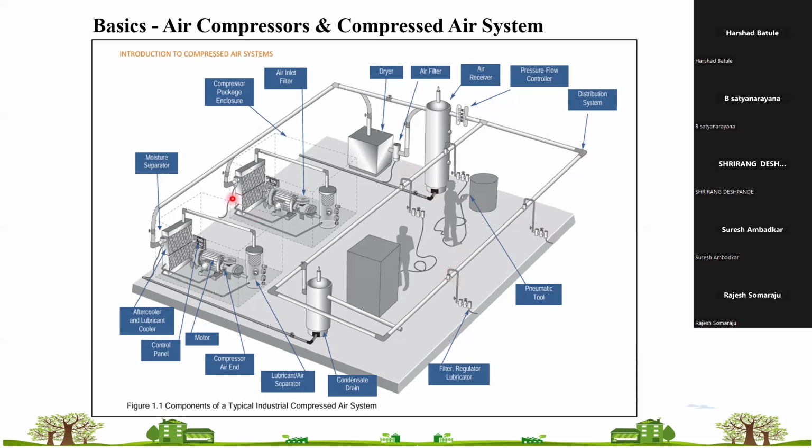You need to run the compressor to survive those leakages, or maintain the pressure in your system. The compressor doesn't understand if there are leakages or actual usages. It understands only that it is at low pressure and needs to build up the pressure.